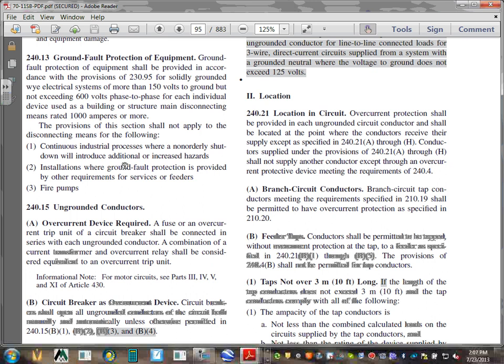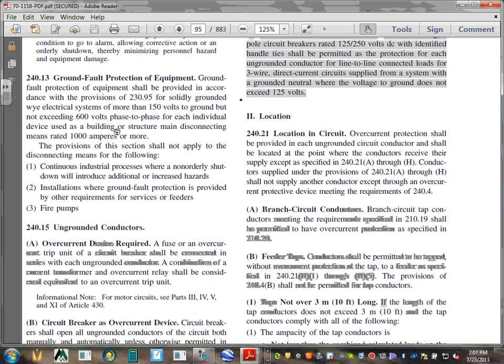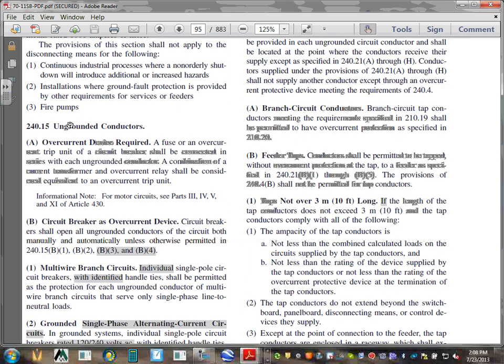No, that has not changed in 2011. I want to say that there's one that says that it needs to be 1,000 amps or more, and at least 6 feet in length. 6 feet in length? Over 6 feet. No, it's the ground fault. I think you're missing. You're talking about access, electrical access. Electrical access, 1200 amp actually, 1200 amp and 6 feet or more. You're required to put 1 door here and 1 door here, with a couple of exceptions. That's the ground fault.